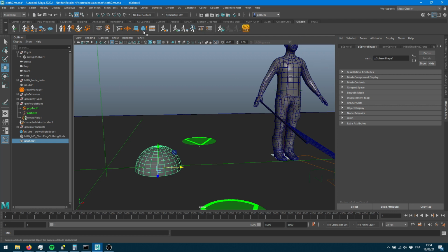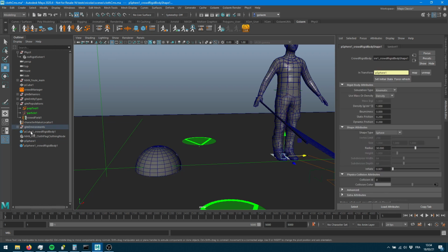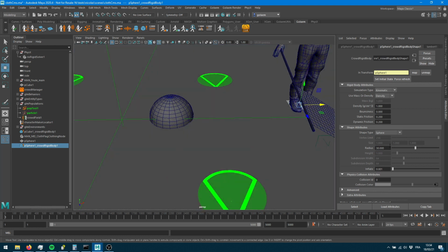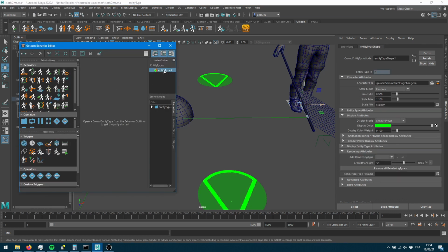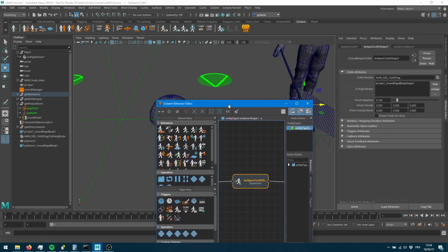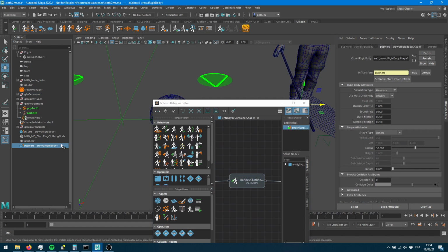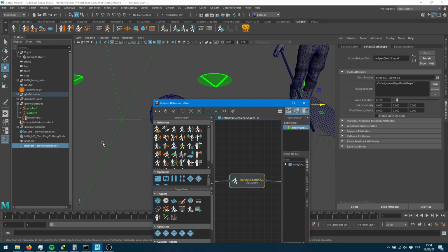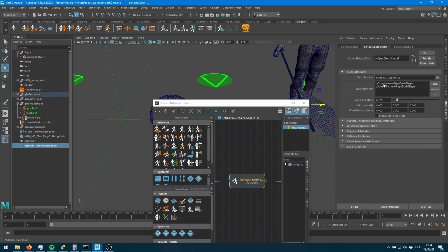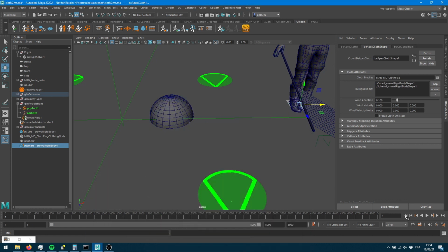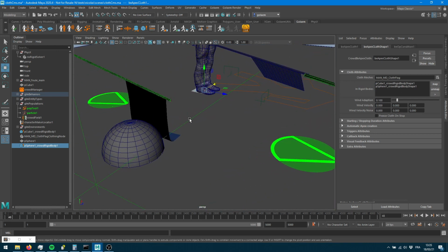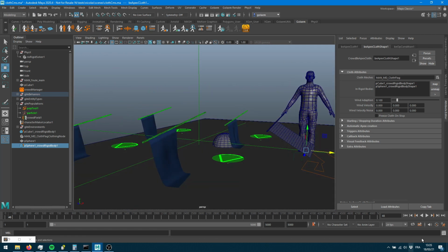So you're gonna select your sphere here, go into the Golem shelf, select and make it a crowd rigid body. So now you've got an approximation of that sphere, a sphere with a radius of 30, and you can now use that new node and go into your Apex behavior, which is used to say that you want to have some physics simulation on your clothes, select your rigid body, press shift to be able to select your behavior at the same time and map it. I was able to already map my cube into this, so this is why my clothes is colliding with the ground. And now you've got clothes which are reacting to that shape here, and those guys here are not reacting to it.